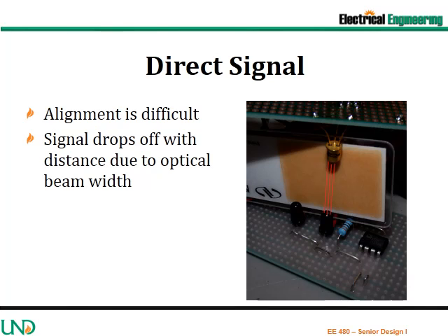To align the laser diodes, an infrared sensitive material shown in the picture will illuminate when the laser falls on it. A shallow angle results in optimal coupling. The small distance ensures consistent operation when applying different signals.